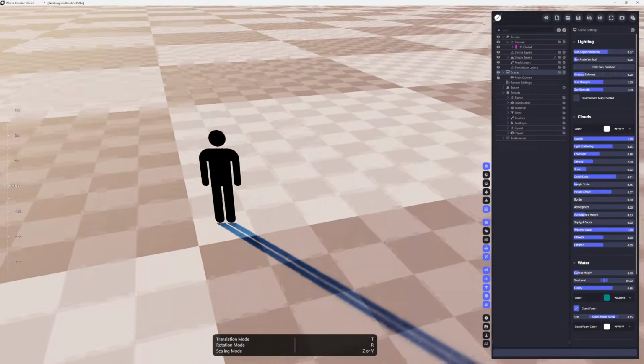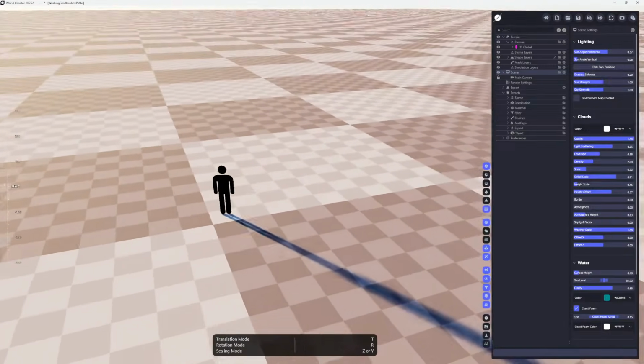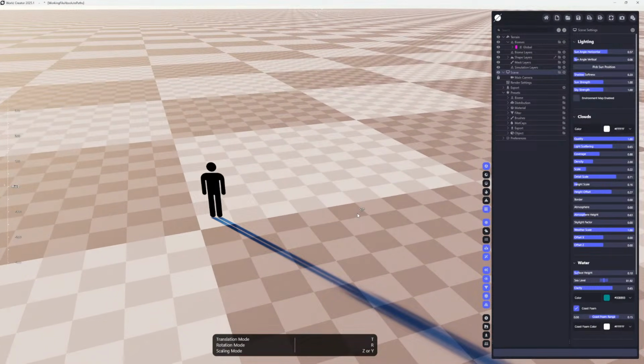I really had to look into it, and there were some limitations about the indices. However, there's a workaround. If you export them as an FBX, import them into Blender and then export out of Blender as GLB, this always works, okay? So I'm going to do a video about this specific case, so you are aware. But in most cases, it just works. No worries about that.